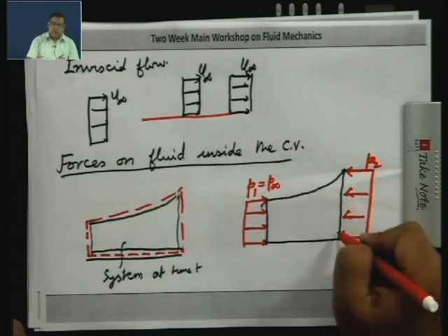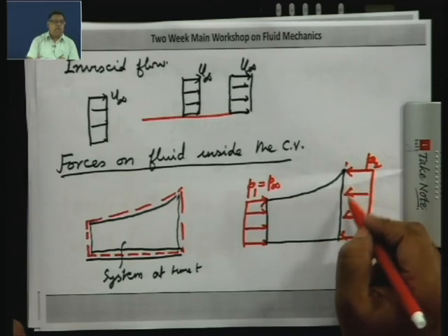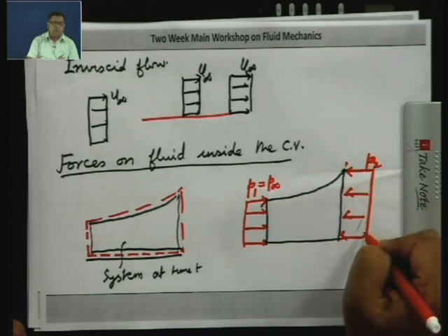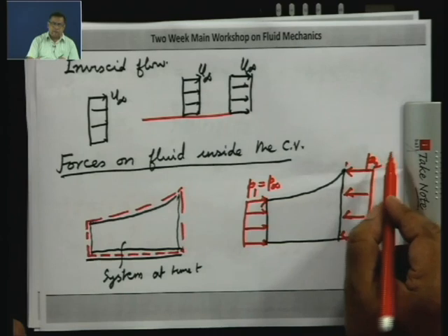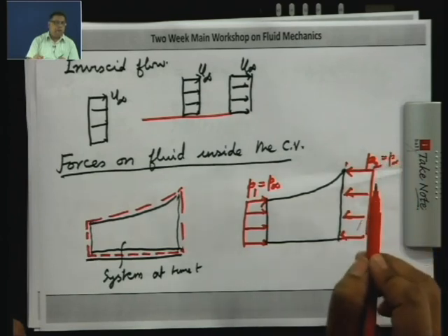We will show that the variation of pressure in the y direction is negligible. Right now, we are going to assume it. So, that is why you do not have a pressure profile here, but a uniform pressure distribution, and we will show using order of magnitude analysis that this also is going to be the same as P infinity.